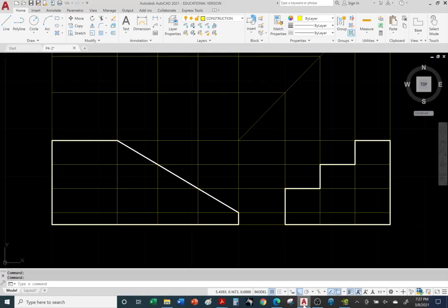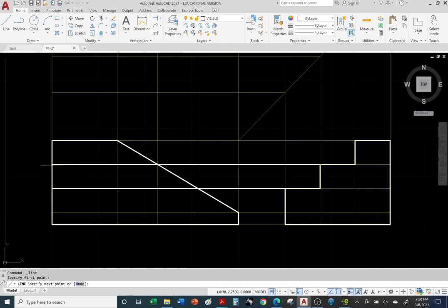Okay, so let's go ahead and create our front view. Be pretty straightforward. Let's go to the visible object layer and use the line command and just go to the corners, project across. I'll go ahead and draw across. You want to have ortho on, guarantees a horizontal or vertical unless it snaps to something. Okay, and right click enter, and then we'll go to the other corner. There it is, right click enter.